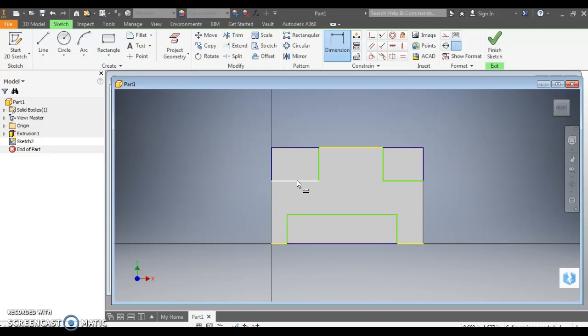So I'm going to click on the bottom, just drag up here. Keep your numbers centered nice in the middle between the left and the right side arrow. Just come up here, keep it centered, and type in, according to the activity, 1 inch. I don't need to add inches. I don't need to add the decimal point because the computer's already been set to do that. Hit 1. Same, come down here, hit 1.